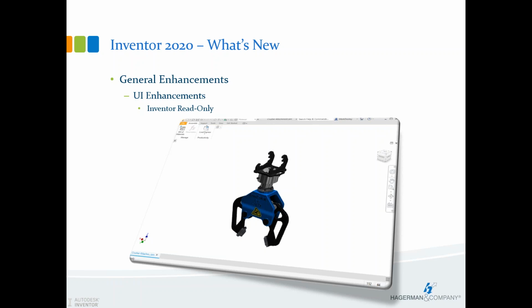So there's not a direct download for Inventor read-only. It's either installed with the Inventor 2020 software once it's activated, or once the trial runs out, it just automatically switches over, and then you've got the read-only option. Now, Inventor View is still available. It's still a separate download. It does not install with Inventor 2020. You can still download it from the autodesk.com/viewers website.